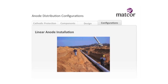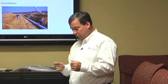Here's a picture of a linear anode installation. You can't really see him, but way in the back there was Glenn Schreffler, our engineering manager. This is a power plant project in New Jersey. Quick story, I think I have a few minutes left. This was a power plant they were building, and they said, we want to put a deep anode system in to protect this one gas line that's going to run around the whole plant. Everything else in the plant is plastic pipe. We do have copper grounding systems, so we know that we're going to have to put a lot of current into the ground because the copper is going to suck up some of it.